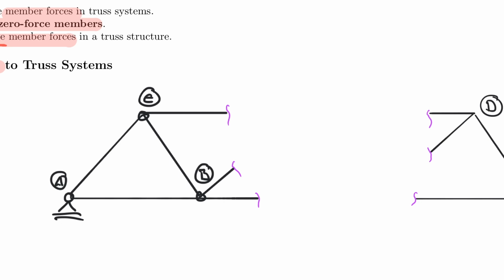So I will now introduce my internal forces, which are only normal forces, just like we talked about before. I have a normal force in line with each member. Similar to the method of joints, they are usually assumed to be in tension first. So I'm going to do that right now. I'm going to assume this here, this would be DE, to be in tension.